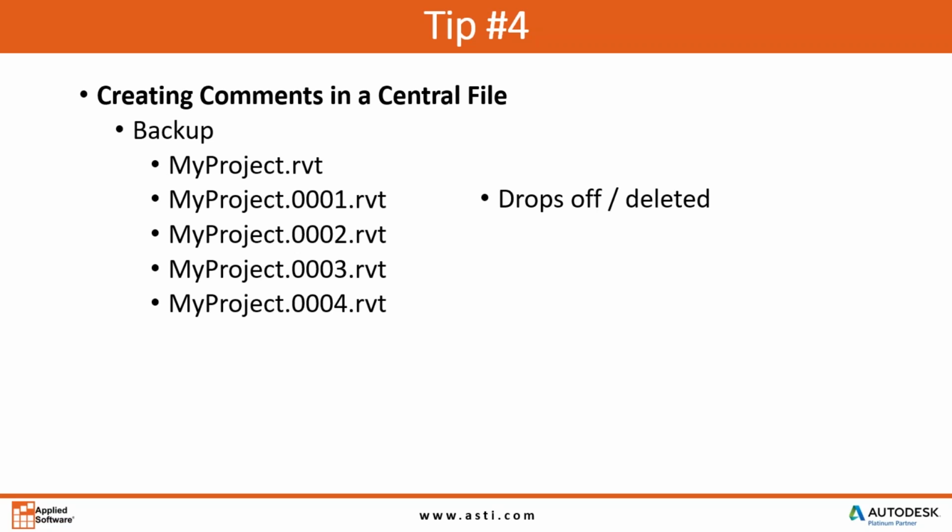You can change this and do some other stuff, but there's usually 3 live backups of your project that you're working on. And this could be central, this could be local. This even applies to regular Revit as well. But these are your backup files. They're full-size backups, right? They're full-size files. You can actually open them directly. But again, most people don't realize that one drops off.